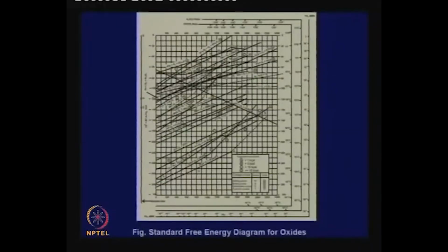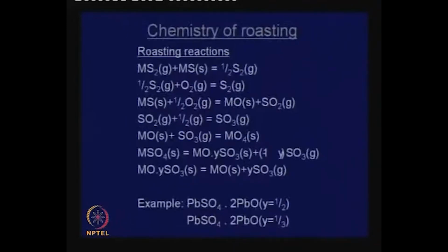Friends, I am reviewing the entire course, and we just discussed Ellingham diagrams and explained why the free energy of formation plots for oxides go this way and the slope is negative for CO. In case you wonder why the slope suddenly changes for these lines, it has something to do with a phase change, something solidifies or volatilizes. This has been discussed, so I will not discuss that again.